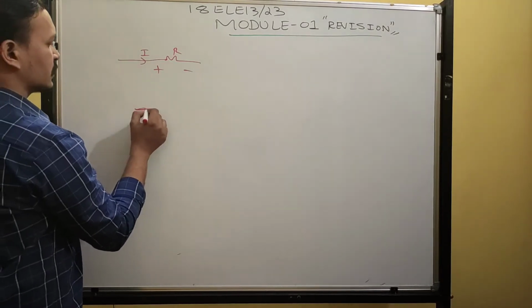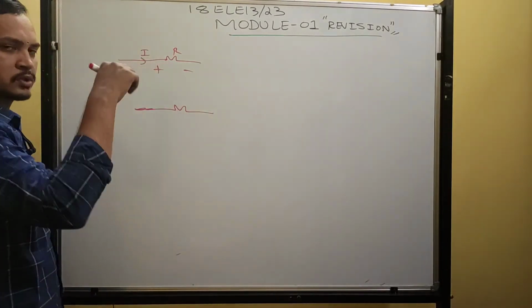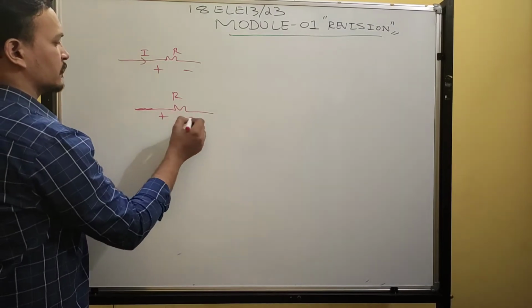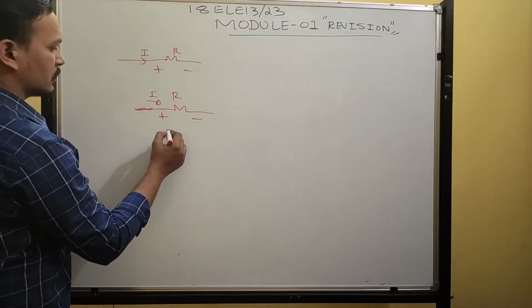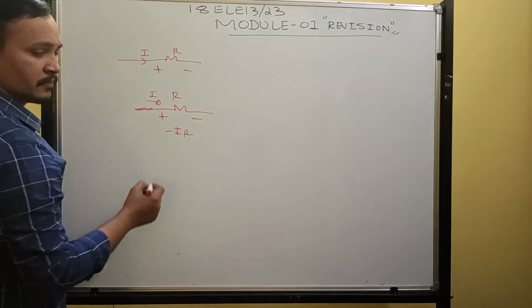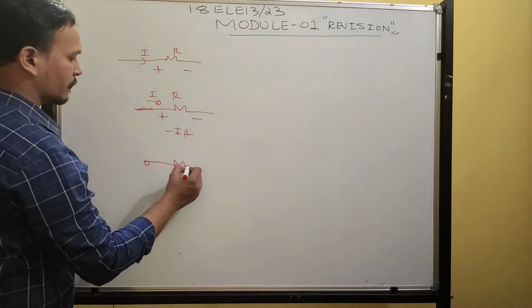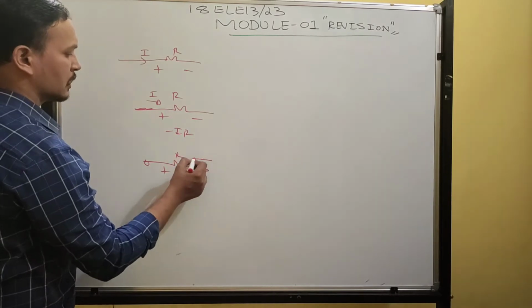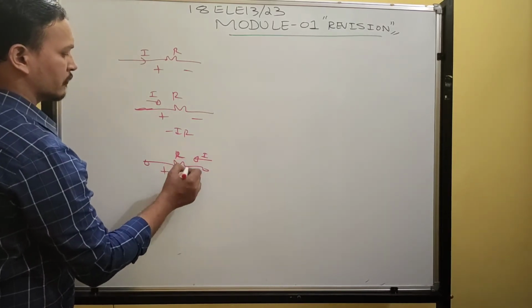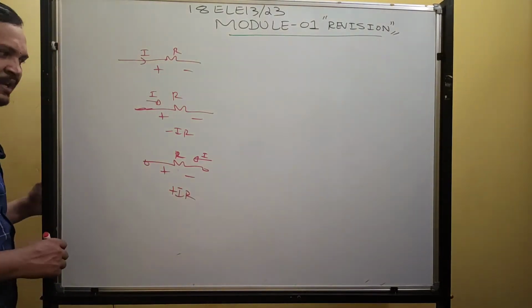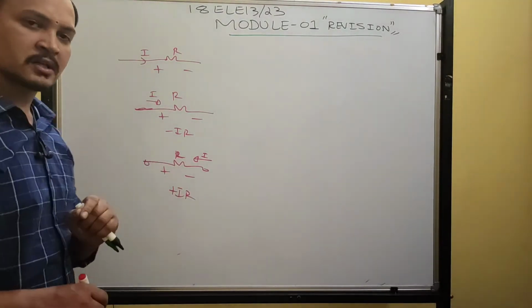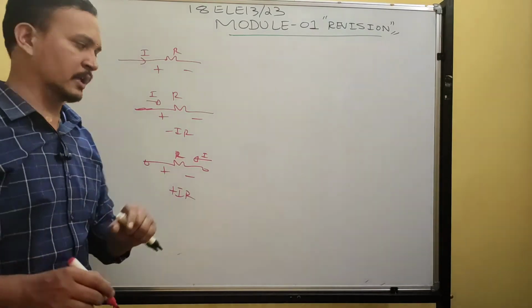Okay. Now for this fixed polarity, how does this current flow? Due to some assumed direction. Now for this fixed polarity of the resistor, if the current flows from plus to minus, then you write drop. Drop is written as minus IR. Next, for the same terminals plus and minus, if the current flows in this direction from minus to plus, then you should write rise. Voltage rise is written as plus IR because a resistor is a bidirectional element. It can receive current in either direction.